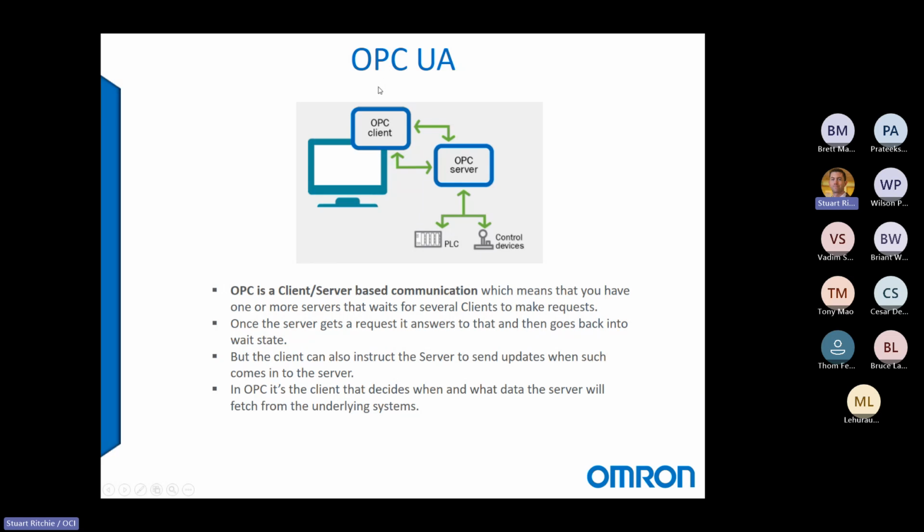So with Modbus, which we'll be doing a demo of next, I believe, we are going to ask for, in this case, 20 bytes from that power supply. And most of those bytes are going to be exactly the same as the last time we read them. So it's kind of unnecessary overhead. It's unnecessary network traffic when we only really care to get fresh data once it's changed.